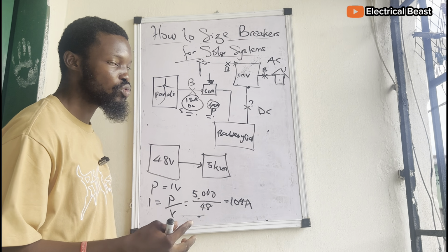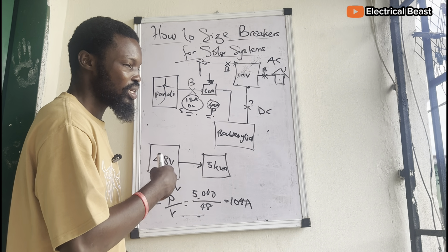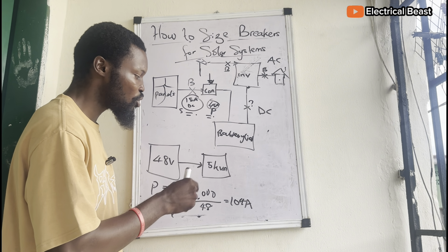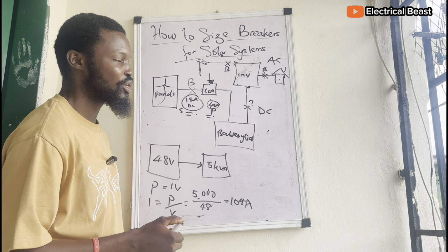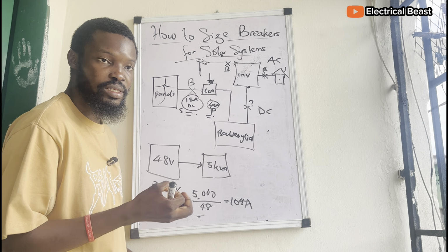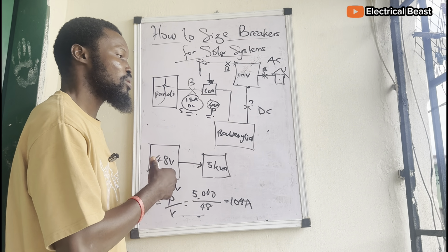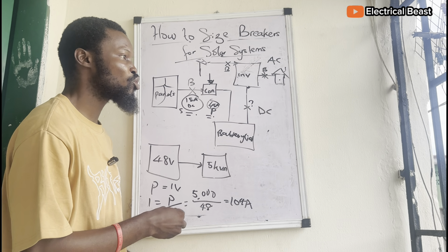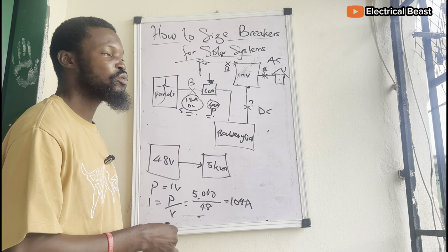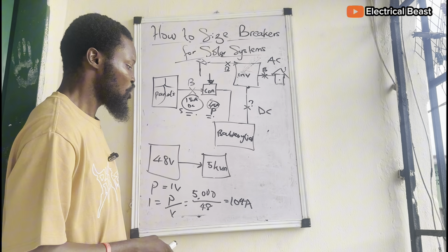If you apply lesser load, it's going to supply lesser current. If you apply more load, it's going to supply more current to the inverter. But for some recent batteries like lithium batteries, you can actually limit the amount of current that the inverter can pull from the battery. Some lithium batteries have discharge or charge current up to 200 amps, even some 250 amps. You can also set the discharge current that you want depending on the loads that you have.